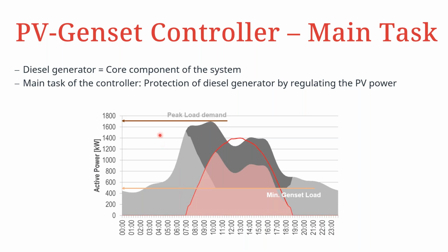So with this power window, as in maxima and minima, you can now estimate the inverter power that will be used for this particular system. Okay, and then given the fact that Fronius inverters have the capacity to be overdimensioned up to 150 or 120%, with that, you would now be able to know what your maximum PV power for injection into the system would be in kilowatts peak.